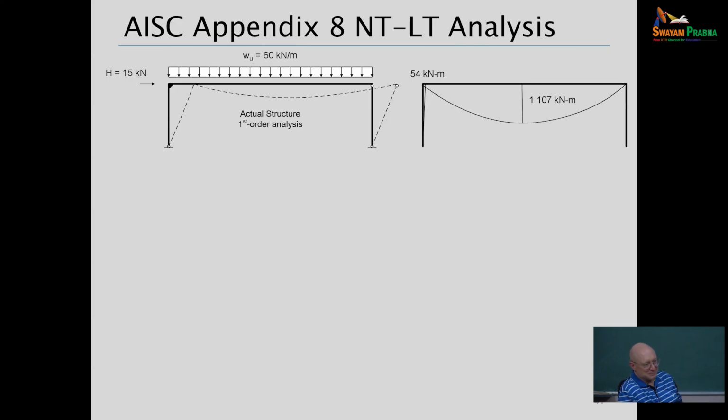So there is inequality in the boundary condition, and so when I take that as a pin joint at the right beam column joint, and then draw the bending moment diagram... If you take the horizontal load away, what would be the bending moment at the left-hand end of the beam?